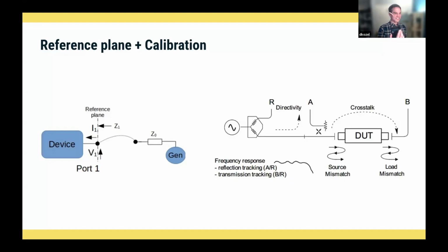But what's the first thing that you do to a VNA? You attach some cables to it. Do I want to measure these two cables? No. I want to measure my attenuator. I want to measure my antenna. I want to measure a filter.